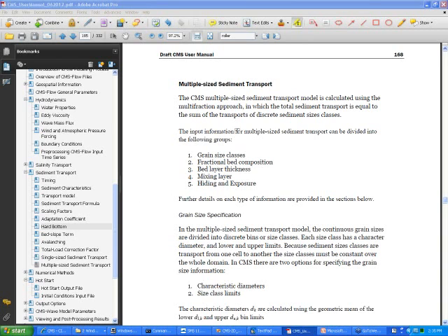Sediment transport, there's a lot of things you can do to post-process the results, and as I mentioned, it's really important to understand how we define the variables when you compare with field data. I've seen people compare measurements of concentrations from an OBS directly to the model concentrations, and they're not the same, right?